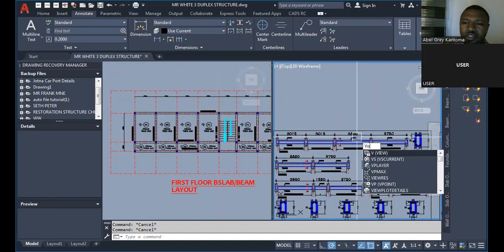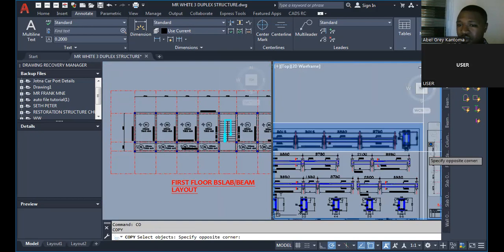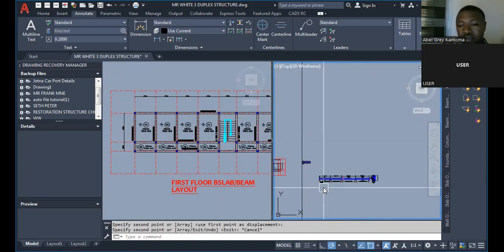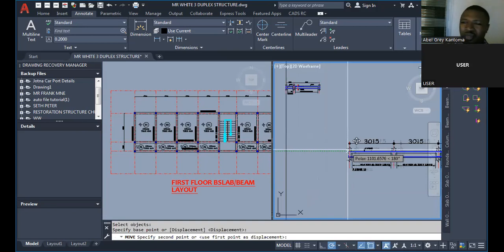Now, one thing you should notice is that on beams, we have the compression and we have the tension. The compression is at the top, the tension is actually at the bottom. So these are the points you need to take note of. Now, there are beams that come singly reinforced, and there are beams that come doubly reinforced. It depends on the loading that is acting on that beam. But right now, what I'm speaking about is based on the design.